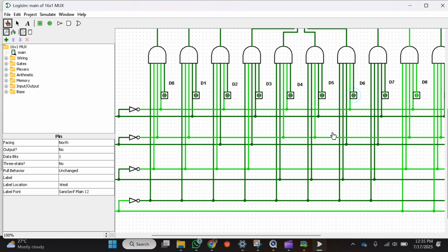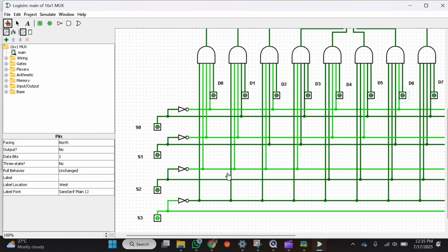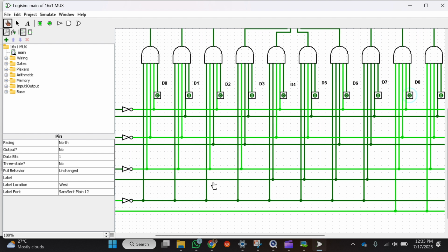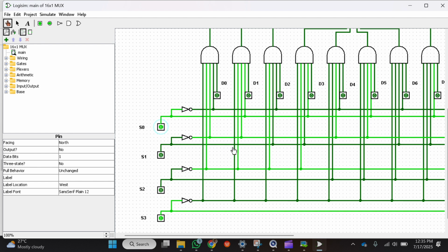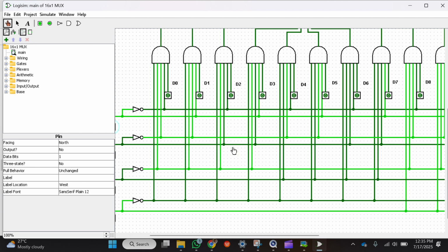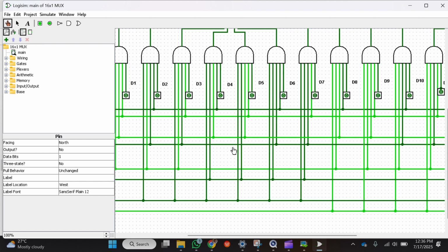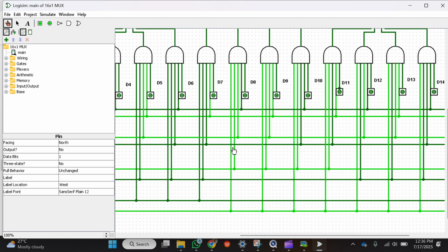So what this basically means is, assuming S3 has been selected, let me switch this one off, the D8 off. Now S3 is being selected, we have to select S0. Now S0 has also been selected. So now we look through and see which are the possible inputs we need to switch on, then we can take it forward. So now we have D9, which is a possible input.